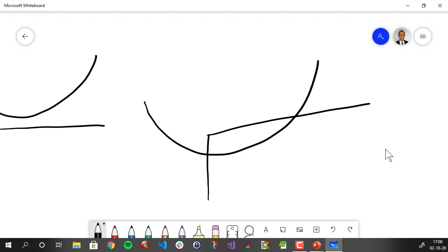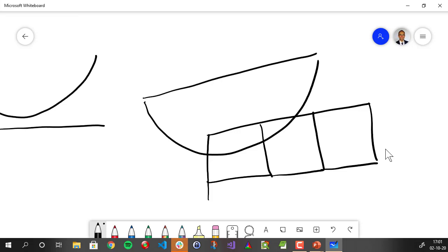So at a particular moment, while Metafor tries to reach the equilibrium, you can have one element in this kind of configuration, which is obviously not correct, because you have some nodes of your mesh here inside your tool. So how does the method work? Here you have your contact elements.